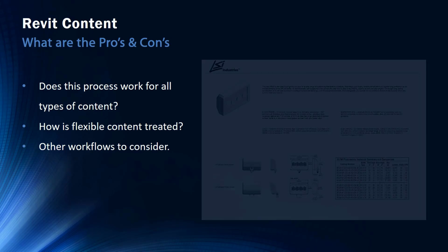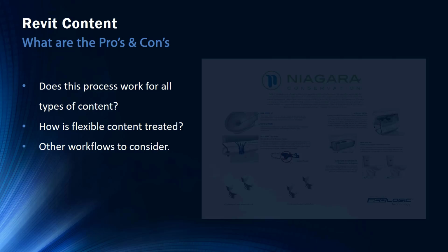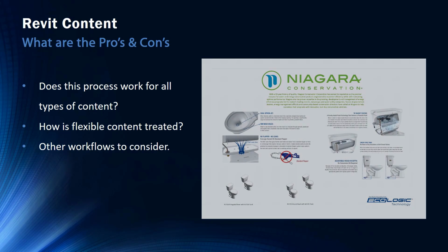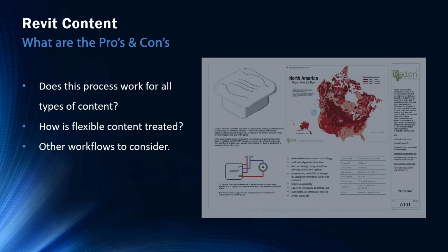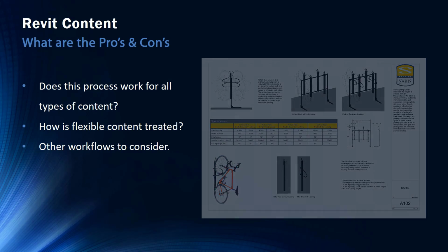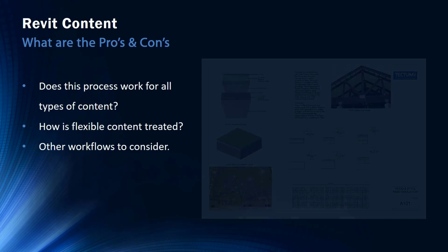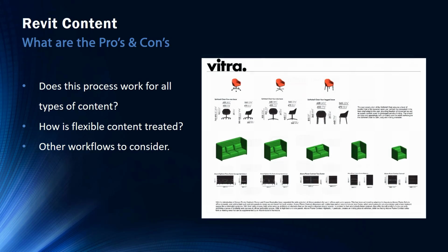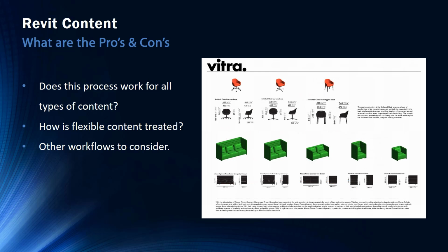A few product groups that do not work with this export example are pipe fittings or cabinetry with multiple door styles and sizes. Light fixtures are just a few examples of some categories that are better handled natively in Revit versus using an export and bringing it into the Revit environment. Light fixtures have a lot of mechanics that need to happen natively in the Revit file in order for it to work properly, to allow for sustainability and lighting analysis and those type of mechanics.